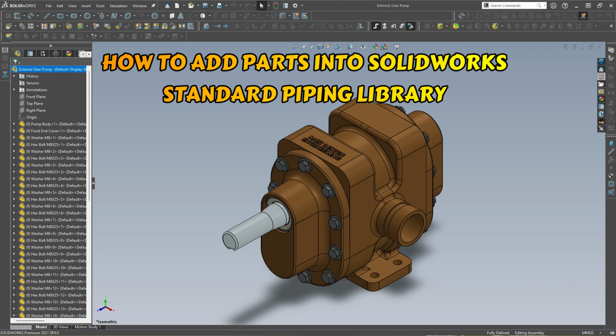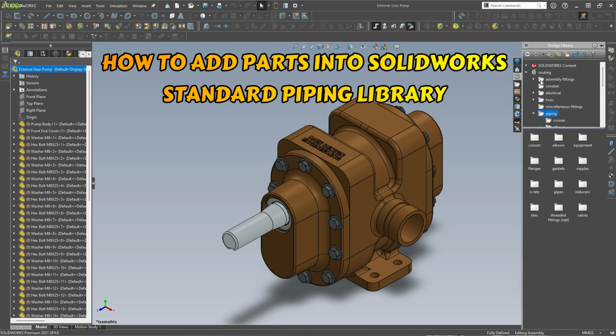Today I want to share with you how to add non-standard parts into the SolidWorks routing design library. Let's take a look at the right side of the SolidWorks UI here. You can find the design library tool panel, and in the routing folder, go to the piping subfolder.